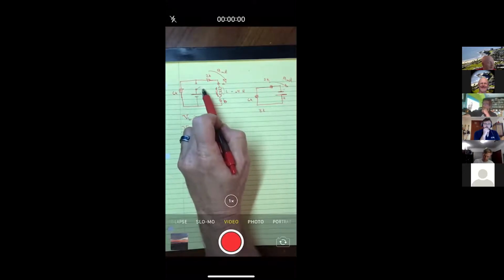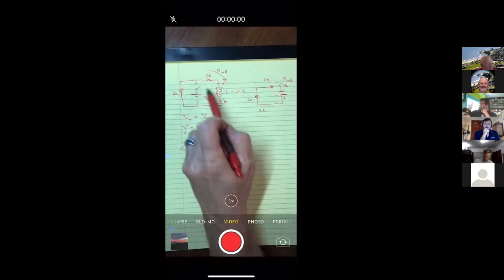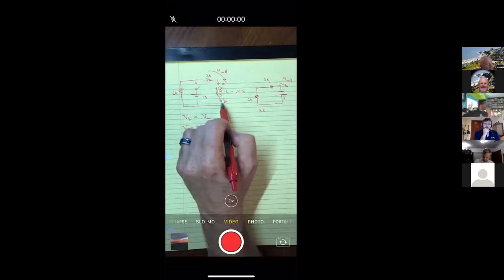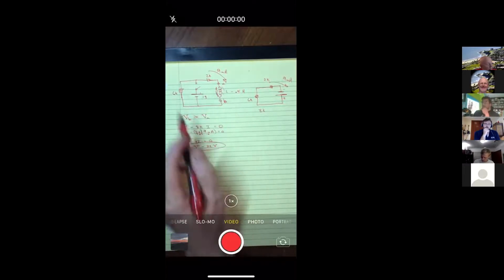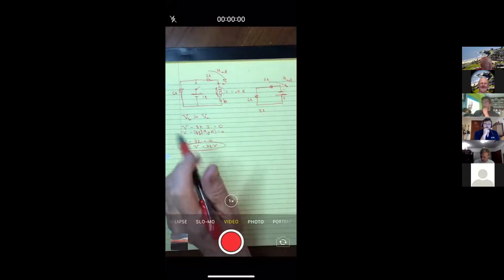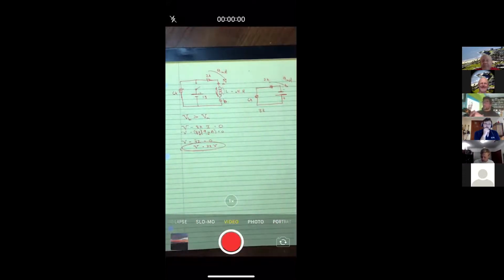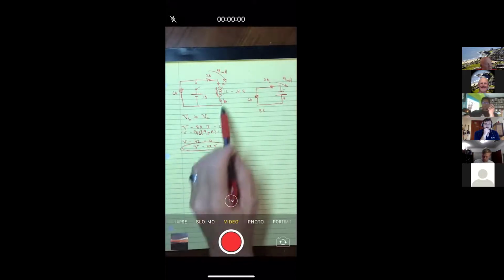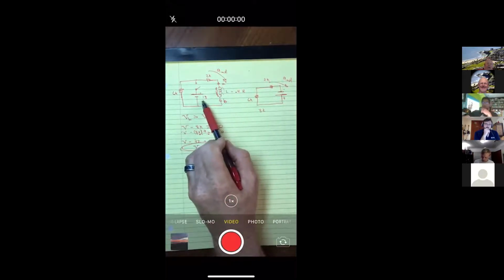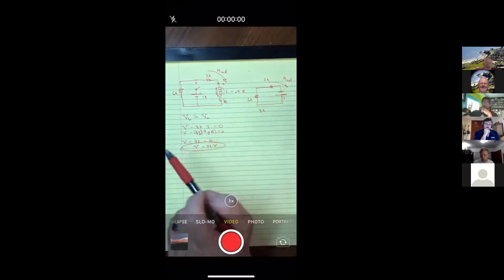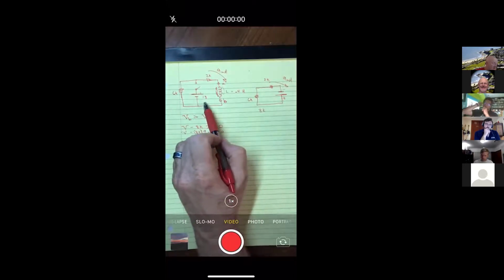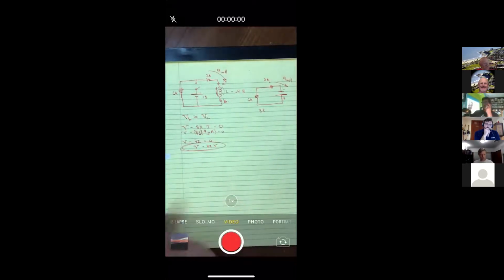But when you open it, that shunt resistor is designed so that it will swing around this way and allow current to go through so that the back EMF doesn't have to jump up real high. Otherwise, you can get so much voltage in your motor. Because notice, if this was a motor, I'm creating 72 volts, but I was only running it with an 18-volt battery. So maybe like this was like a hand drill. One of those cordless hand drills on 18 volts. And I'm running this on 18 volts, and I shut it off. All of a sudden, boom, I've got 72 volts in my circuit.